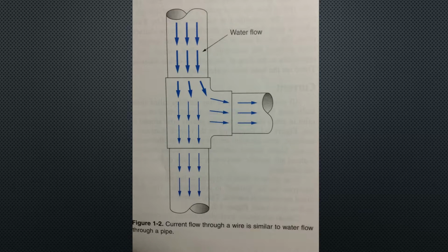Voltage is a measurement of the EMF produced by a source. The volt, symbolized with a capital V, is the basic unit. It is defined as the potential difference between 2 points in an electric circuit when the energy needed to move 1 ampere between the points is 1 joule. Note: in formulas, voltage is represented by either capital E or capital V. The capital E will be used in this text.